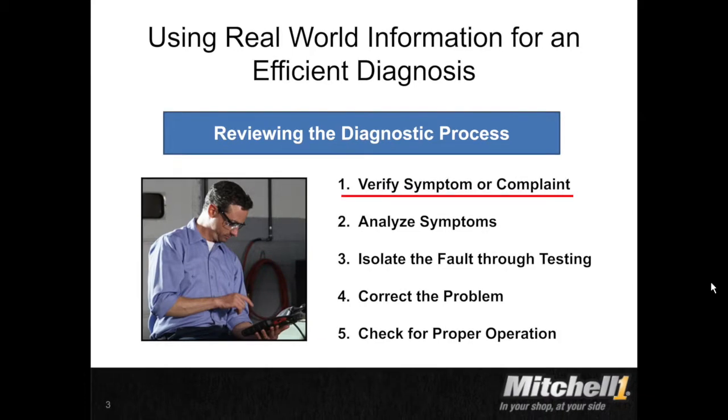All right, the first step I want to start with is number 1 here, verify the symptom or complaint. This is really the reason the customer brought the vehicle to you to begin with. Without the symptom, the customer wouldn't be here. We're really doing 2 things in this first step. We are understanding the problem, and then we are replicating the problem.